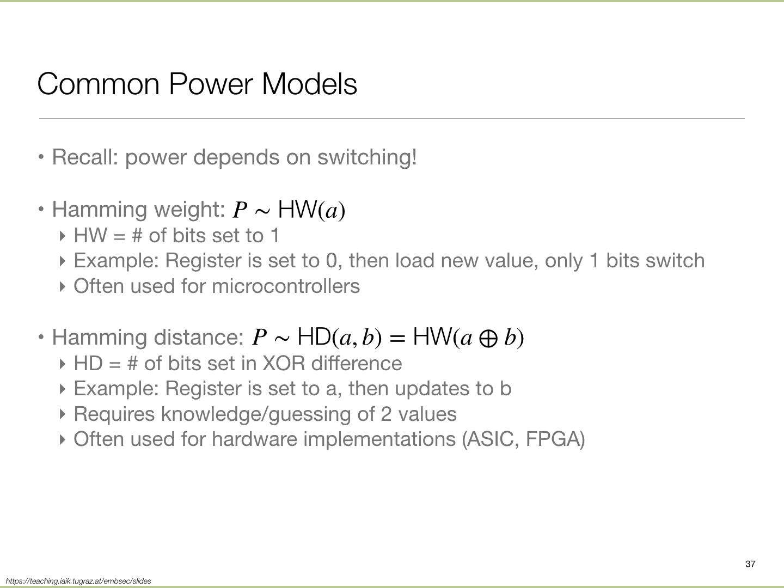So the challenge with template type attacks is, I may train on one device and now I'm trying to break a different device whose power consumption is somewhat different, because maybe it has more leakage in it, or maybe because the temperature was different. So there are all these confounders. With differential power analysis, you basically look at how the power differs under different input settings, and you try to rule out the common errors that affect these devices.